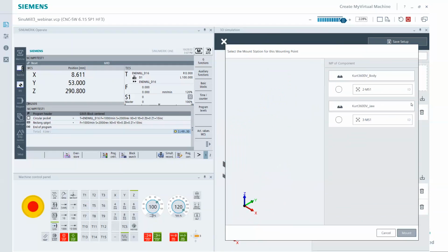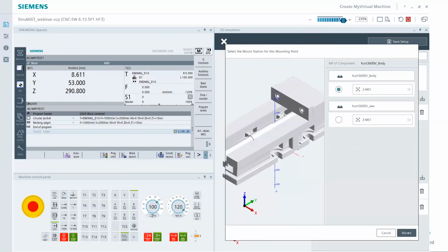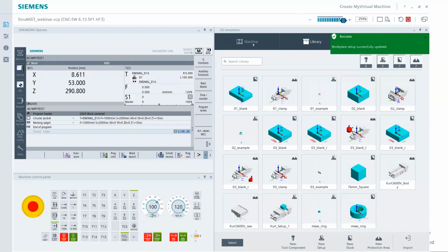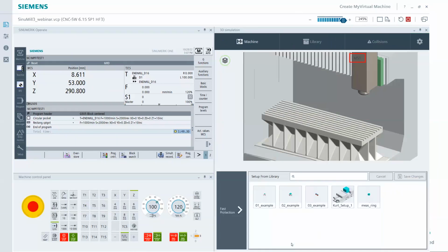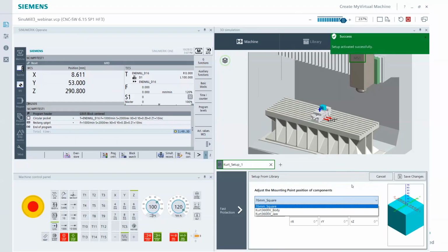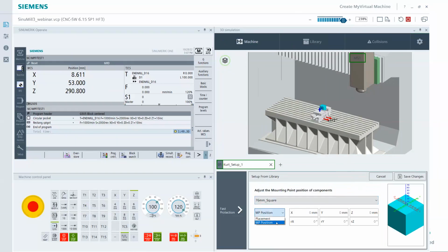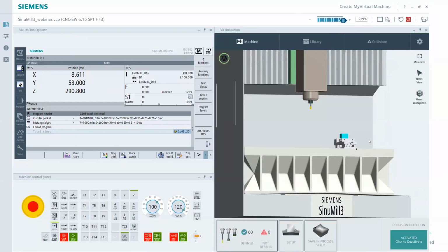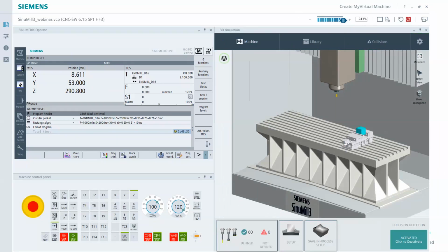Now do the same thing in the stock. So go to this little icon, and now I want to link it to the body. I want everything linked, in this case, to that one common item, my body. So once it's all been saved, save the overall model. So now when I drop it on the machine, plug it on the machine, I still want to go to MP position, but I just picked the body, and since everything's associated to the body, and you see one number, the whole thing moved.